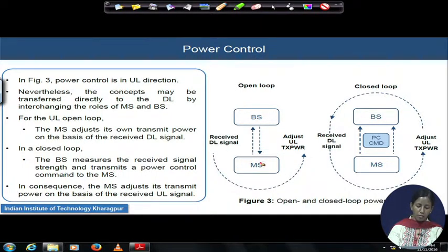It can also assume the approximate channel condition, and from the received signal it can also do channel estimation. So, understanding the channel condition and received power level and measuring the distance, it can now change its transmit power. If the channel condition is really good, it will not transmit at a very high level. If the channel condition is bad, it needs to put in more power to get the transmission through. So it will adjust the transmit power level in the next uplink transmission.